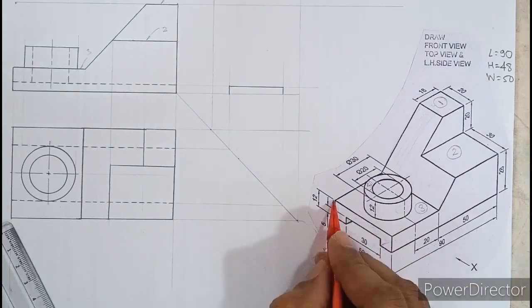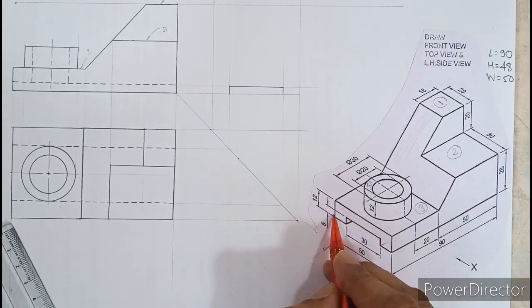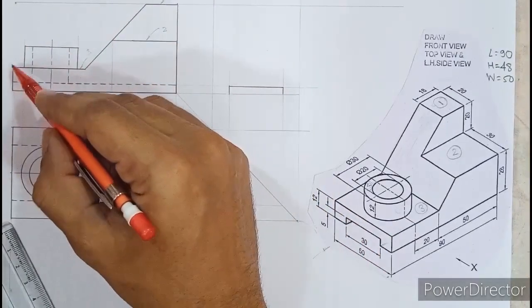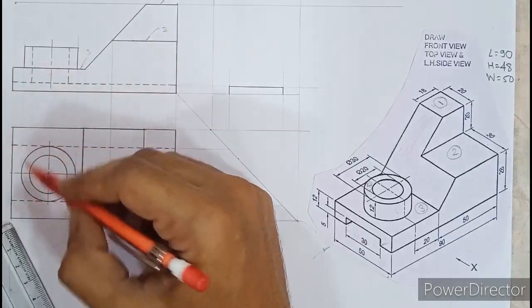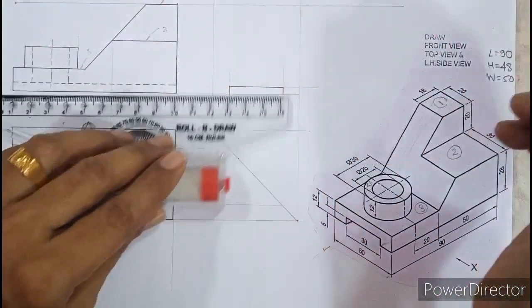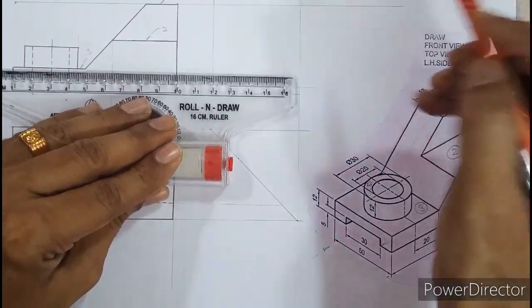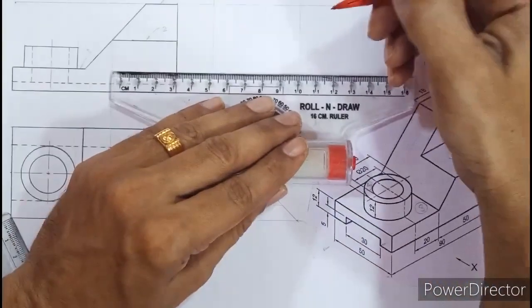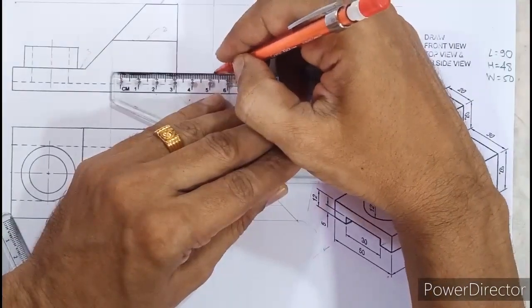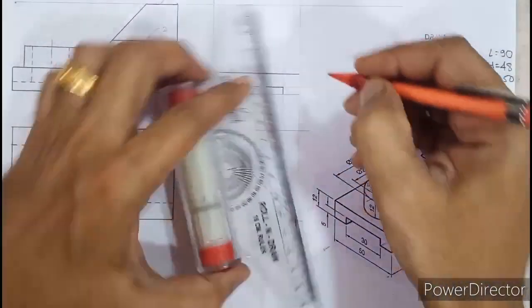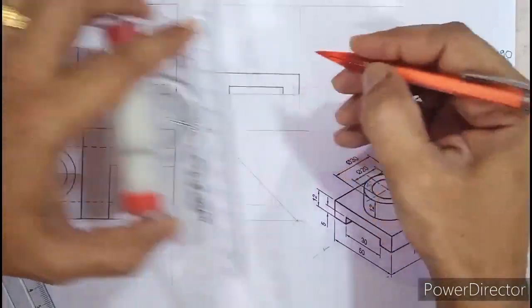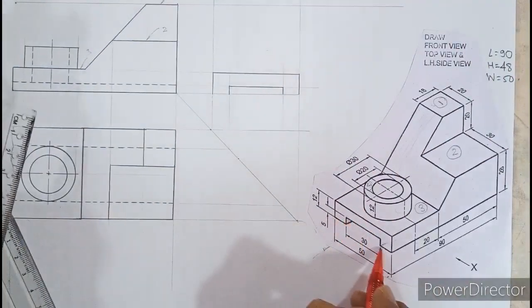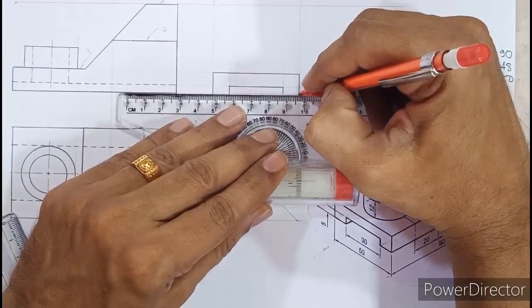Okay. Similarly, we have the outer C. Outer C height is 12 and width is 50. So 12 mm where we have drawn? Yes, it is this height. This is 12 and 50 is the total width. So this 12 mm I need to project in the side view. So I'll extend this here. Okay. So let me darken this. I'll bring this down. So very simple. Orthographic is a very simple topic. Whatever you see, you have to draw. So you can see this C type connected here. So that we need to connect it like this.